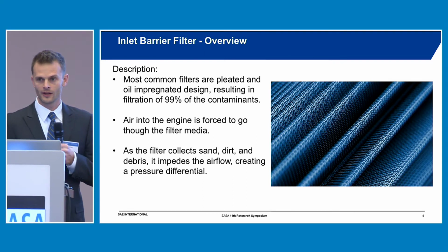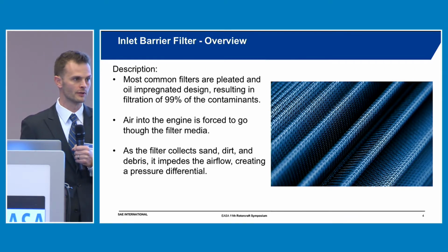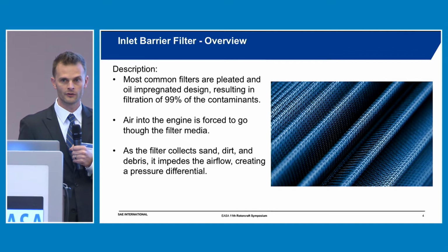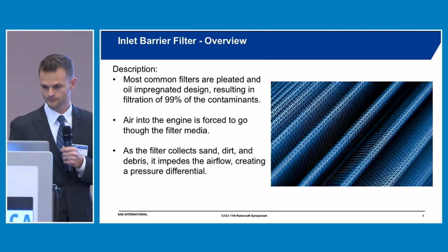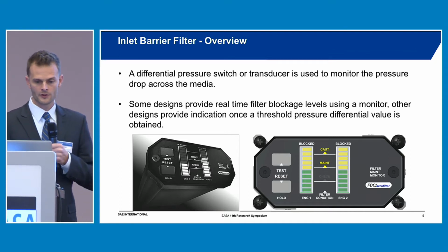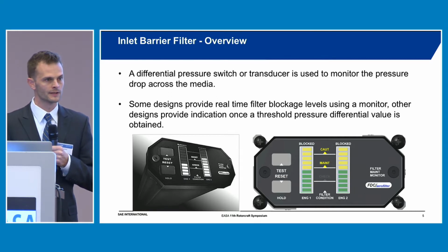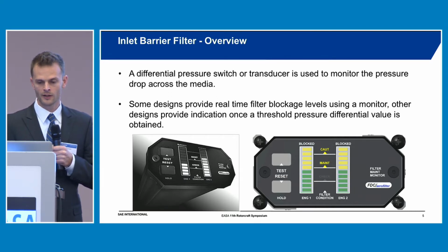The media collects the sand, dirt, and debris, and as that continues, a pressure drop builds over the filter or creates inlet depression. From there, these systems have a differential pressure switch or a transducer, and that measures the pressure drop or inlet depression, pressure drop across the filter.